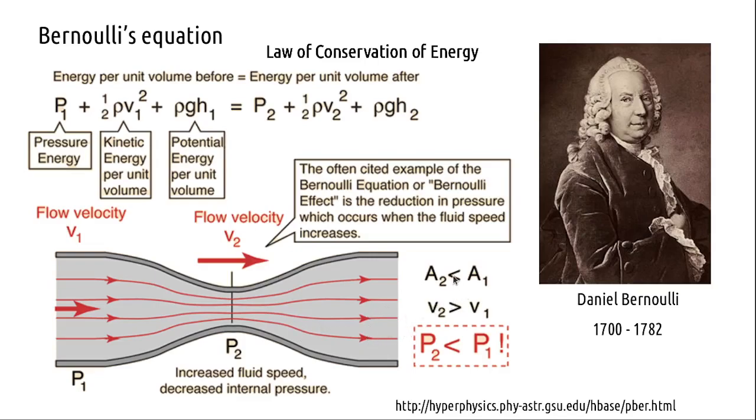Consequently there will be a reduction in the pressure because A2 is less than A1. So this is the key thing there. Actually there is a transformation of energy from one form to the other, static to dynamic. That means the static pressure energy is converted to kinetic energy. So that's why V2 increases. So it balances between these 2 points.